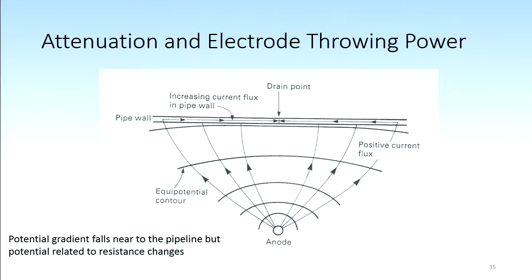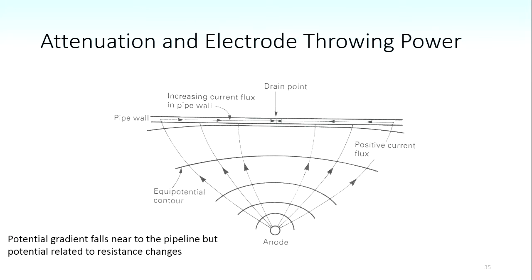And what you're aiming to do is to get the flattest, most even potential on your pipe. So the contour next to the pipe is relatively flat. That's rarely achievable. There are all sorts of things happening. It's a dynamic system. There's noise because of other things happening in the environment, and variation in the soil and so on. So this is an idealized situation.